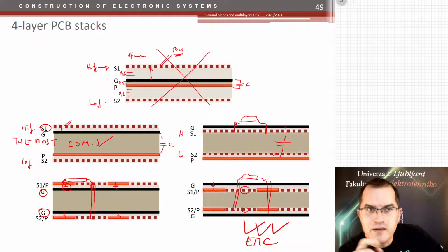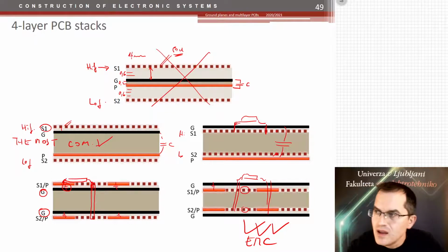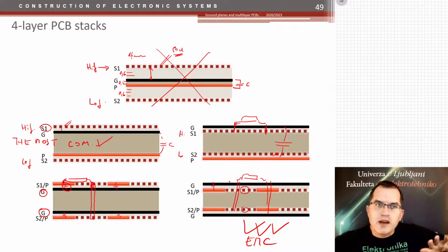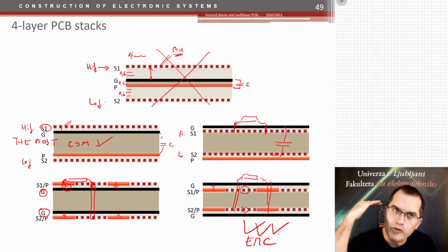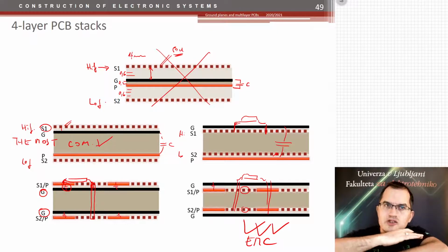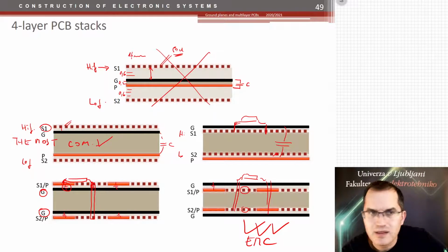And also, even though you have to use wires to connect every single pin of your devices on top, you still have a lot of space below to connect tracks, because there is no interference of the ICs. No pads are on your way. So you can make really dense tracks going all around in the mid layers. And then you have top and bottom plane shielding everything from the rest. So if you have an EMC problem, this is a go.